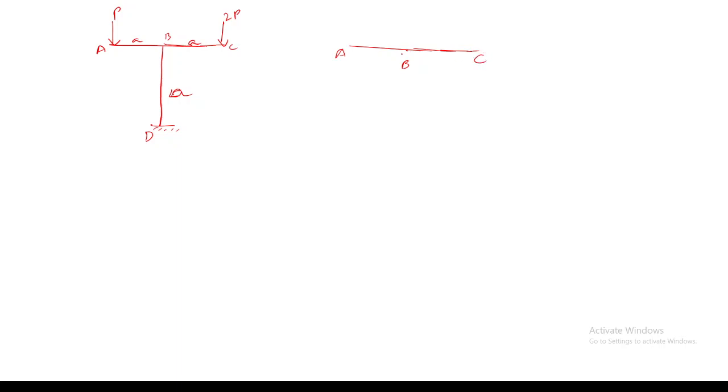what will be the reaction due to this loading at point B? Shear and bending. Yes, it will be shear force and bending moment. Shear force of magnitude 3P.